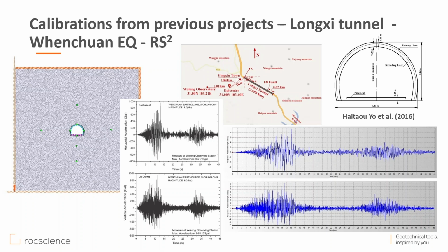Then they used another modeling, with both horizontal X and Z motions, transverse and longitudinal to the tunnel axis, considered without vertical accelerations, and all 3 motions in the third option. This is done to individually investigate the effects of the longitudinal and vertical accelerations on the response of the tunnel, since for the design those are often neglected in reality. So I also mentioned that it's very, very important to use not just horizontal but also vertical motion.